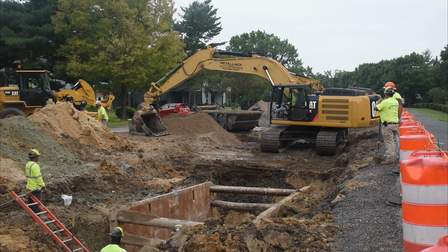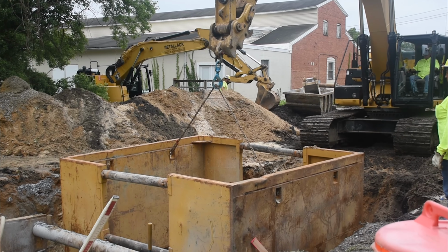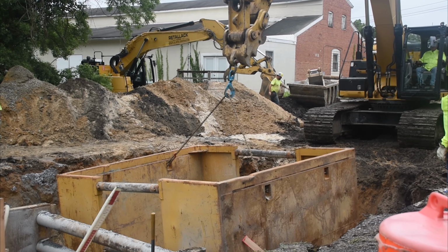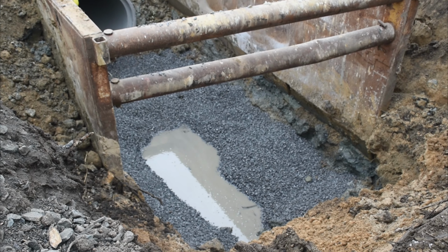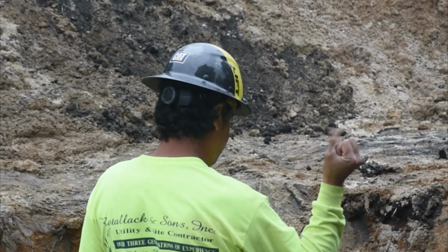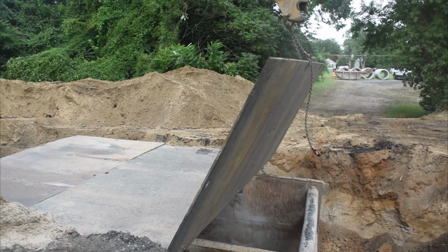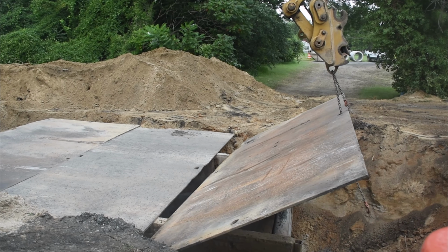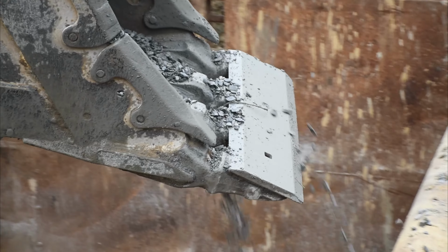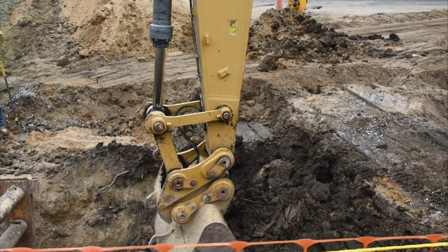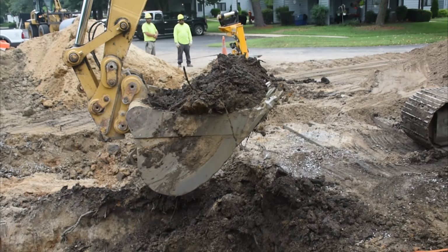Installing storm drain at these depths requires special construction techniques and equipment. For the safety of the crews, shoring of the excavation trench was mandatory. This shoring was done using trench boxes that protected workers and allowed for the installation of 2 pipe sections, or 16 linear feet of pipe before being pulled to the next section of newly excavated trench. Working at these depths, getting 5 pieces of pipe or 40 linear feet installed in a day was considered a good day.